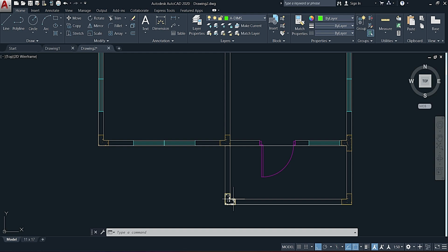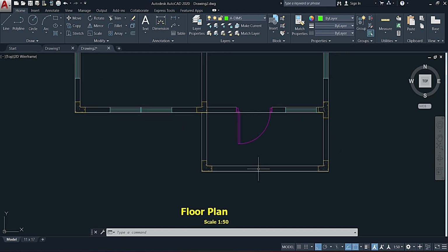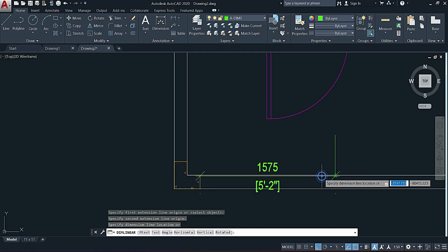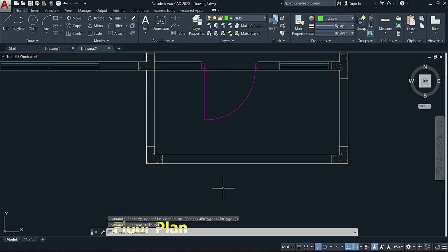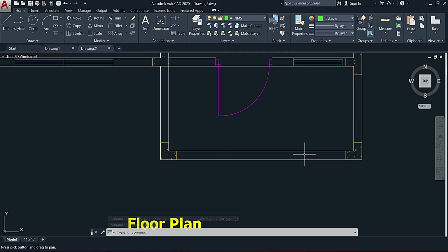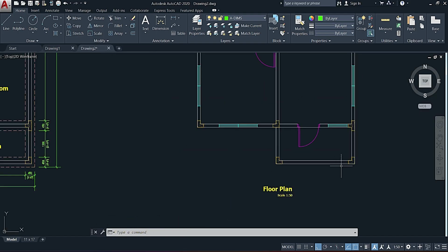The only opening that is not sorted out now is the veranda opening. How is the veranda opening going to be looking for us? All right, I will probably, let me see, where is the center of this line here or wall? That's right there. All right, so I want to put a column right in the smack in the middle here to divide the space, but I need to check to see what's the gap between it. All right, because since it's 5 feet, the overall thing will be 12. That means this is good because we can have a beam stretching 10 feet. All right, so we'll leave that there for now, blank.